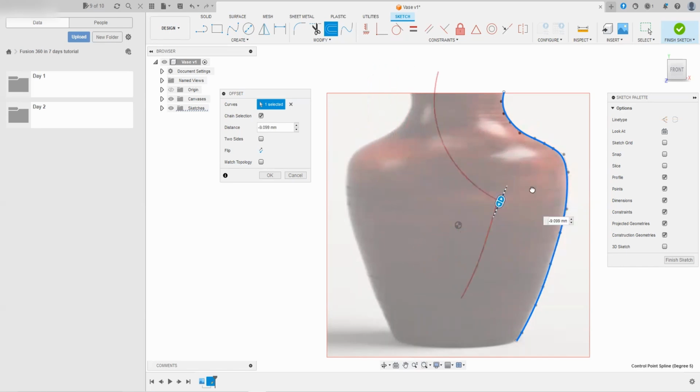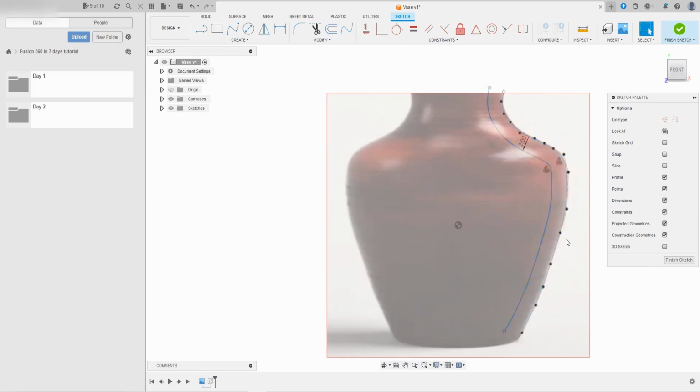So that being said, let's go ahead and choose the 2 millimeters as our offset towards the left while matching the topology of the original spline. Press on OK to confirm the choices, and there you have it. The offset has been created, copying the original shape of the spline that we initially made. Let's continue using the sketch functions to turn this into a closed shape so that we can later use the Revolve command as we mentioned earlier.